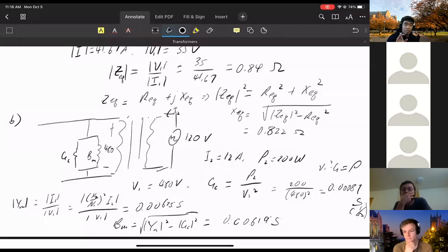Normally the transmission line creates a standing wave, and the propagation speed is fast enough that the delay is below a few microseconds. So basically, what GPS gives us is a few microsecond accuracy, and that's normally good enough for phase measurements.